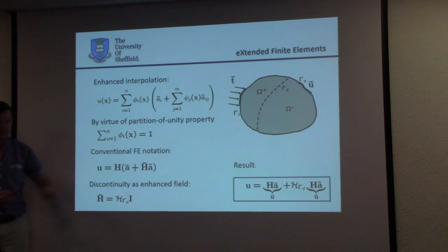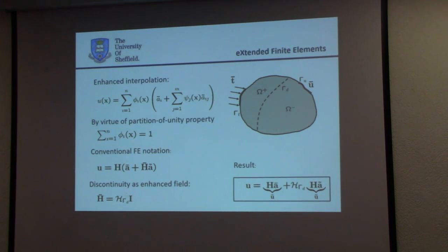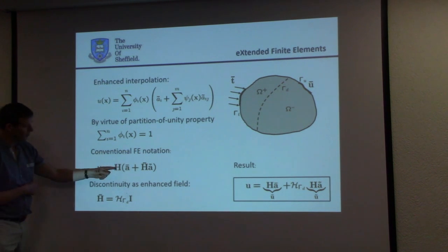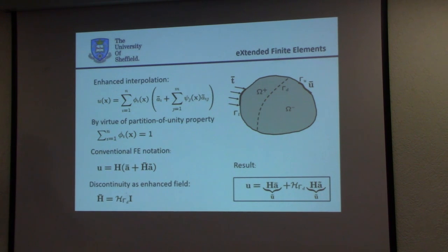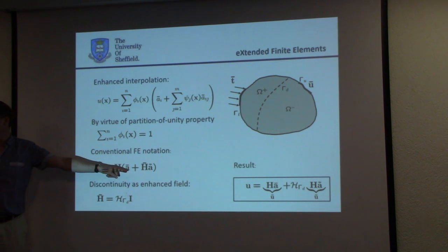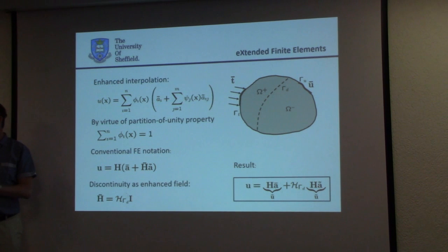But you multiply the additional functions by the original polynomials, and that has the advantage that you keep this enrichment local. If you have one node here with surrounding elements, they are non-zero only for the support of these elements. So these singularity functions, the additional functions, are only there in the surrounding of the enriched node. Farther away, they don't bother. It's a big advantage, since you don't need the singularity functions far away.